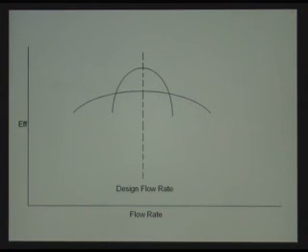Now, a lot of those points will help dictate what kind of efficiency curve shape you're going to want. If you have a very fixed process that doesn't change very often, or when it does change, it doesn't change very far, you may want to have a fairly high peak efficiency to reduce the amount of energy required to do the compression service. And then a high roll-off doesn't affect us because we never operate out there anyway. If your process flow rate potentially could span quite a ways, you may want a less high peak efficiency, but one that doesn't drop off as you get away from your design flow rate, which gives you a better overall operational range.